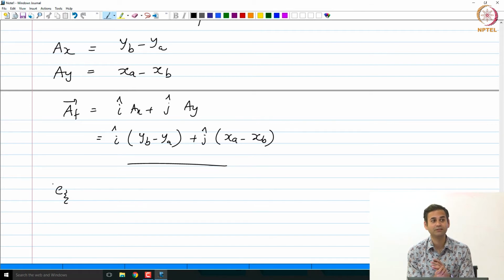Because it's unstructured. You may recall if you have a finite difference kind of mesh, then you would probably use one particular transformation which will relate your entire xy into some curvilinear geometry. But here we are talking about an unstructured mesh where each and every cell can be in its own directions. As a result, you will have a local coordinate system for each and every phase. So these e xi, e eta are specific to the phase in question, and these have to be computed for every cell for all the phases.